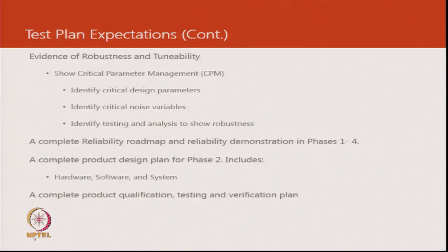And then if there are new softwares to be developed, so while air conditioners look like a mechanical product, the control algorithms that are there involve electronics, and then there is a lot of feature integration that happens based on those algorithms. So to give you a glimpse, we may have an algorithm which ensures that the compressor runs for a minimum of 3 minutes after it starts, or a minimum of 1 minute after it starts, so that oil returns back. And when it is switched off, it is off for a period of 3 minutes, so that there is no stress because of pressure difference across the compressor. So these are 2 examples.